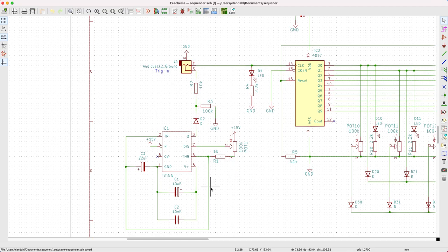A couple other details. It is really important when dealing with these CMOS chips to not give them spiky signals or stuff with a lot of noise. So I have added filter capacitors to smooth out the power draw on the 555. One well-known disadvantage of the 555 is that it produces spiky outputs by suddenly surging on its power draw when it flips state.